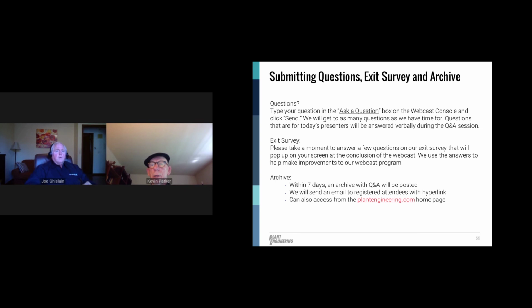So it's really a hard one to do, but you really need to go through and question, because if you ask somebody from production or somebody developing equipment what quality they need, they're going to say the absolute best, of course, and that isn't always the case. To do that, you have to put in a lot more equipment. So there's a difference between plant air and instrument quality air, especially if you need oil-free or if you need low moisture. That takes you from a refrigerated dryer to a desiccant dryer, which is much less efficient.